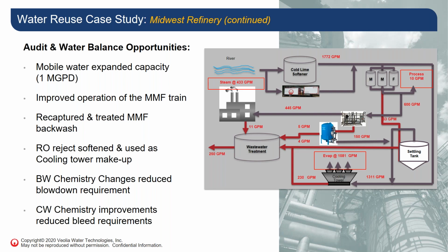With all of that happening, a change was made in the boiler water chemical program, which reduced the blowdown by over 38%, not only reducing wastewater generation, but also reducing the loss of BTUs and chemicals that were emanating from the higher blowdown levels.